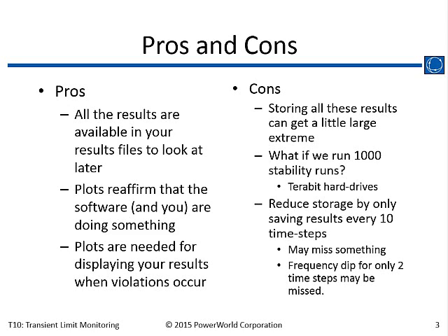The downside is that you have all of this data, so you can get into lots and lots of storage of things maybe you'll never look at again. And we talked about the option earlier when you're saving data that maybe you're not saving everything every time step because you want to cut down on the amount of data that you stored. So in the process of skipping time steps, you may have missed something. So you may have missed a frequency dip that could be significant.